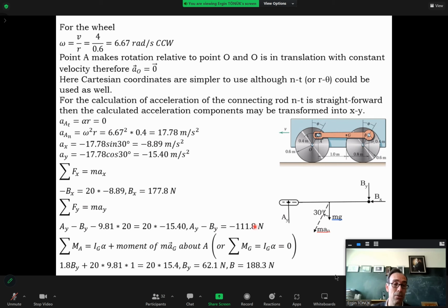Now, if I also write this expression, I'm going to get another relation, moment of Ay, moment of By, and what else do I have? This doesn't have any moment. I'm taking moment about G, so mg has no moment, is equal to 0. So by using this relation and that relation, I could solve Ay and By.